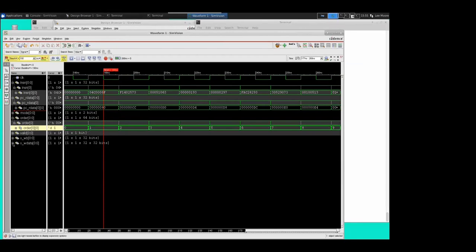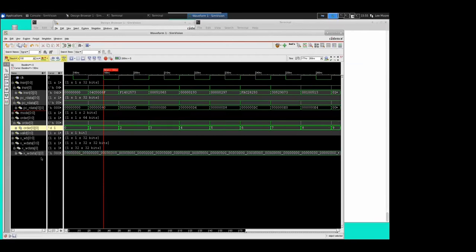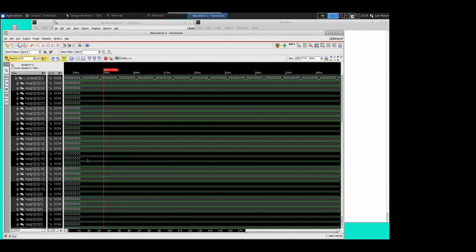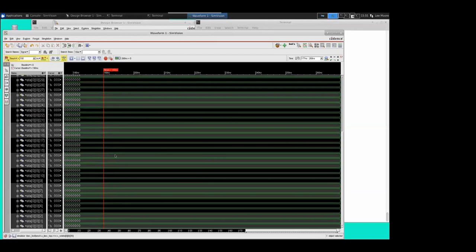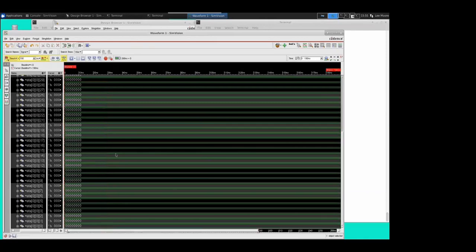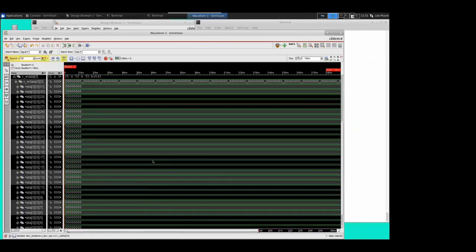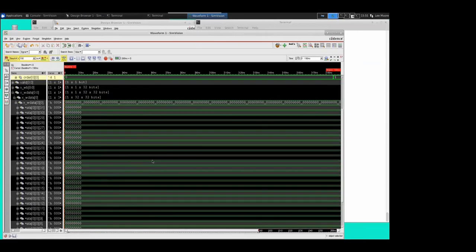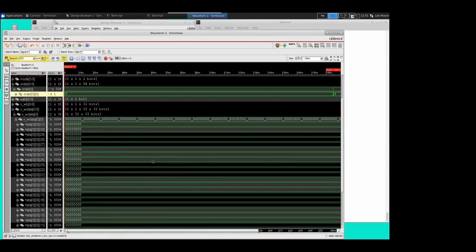And then we see the individual registers on our hart 0 for issue 0 of all of the GPRs 0 through to 31. But as we've already discussed, there are no changes to these registers as we're executing because of the problem we have already investigated here.